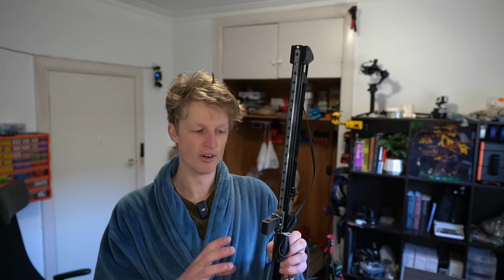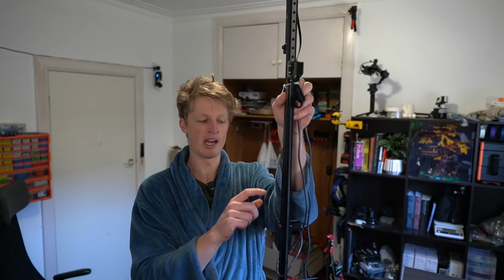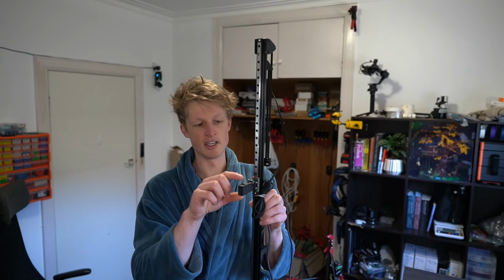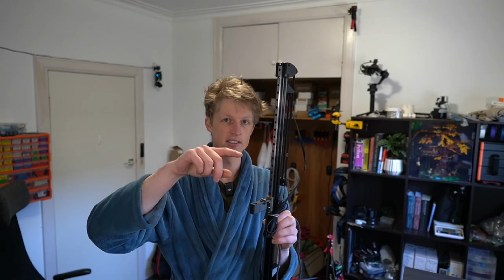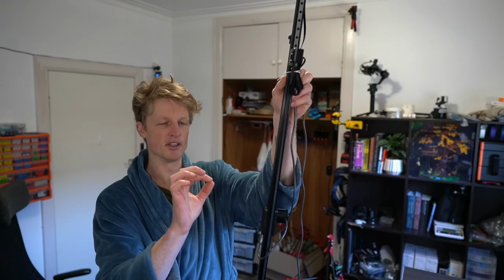My plan for how to use this was threefold. The first step involves calibrating how many revolutions, or how many ticks of the encoder, is equal to a given linear distance. Right now, I know the radius of the pulley here, and I know the thickness of the belt, but as we found from the hand calibration with the string wrapping around that spool, I really don't think I'd be able to theoretically estimate what the effective radius is that the belt is running around that pulley.